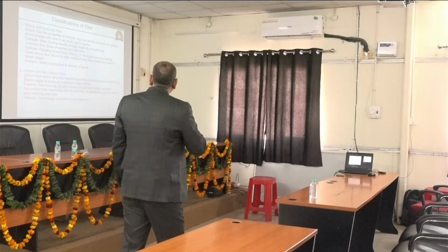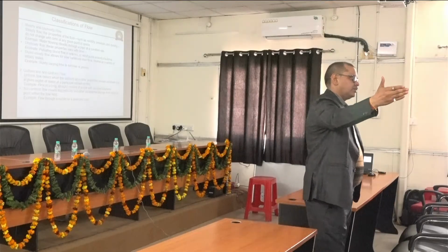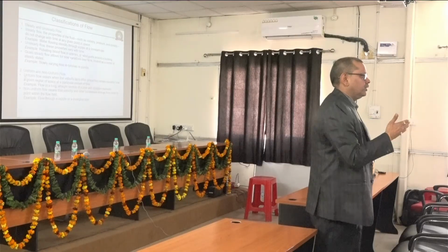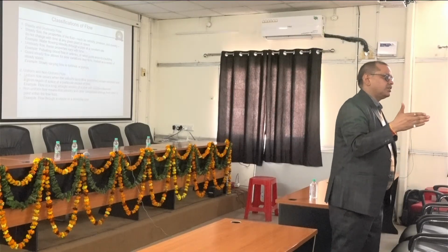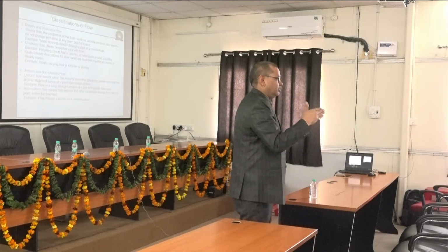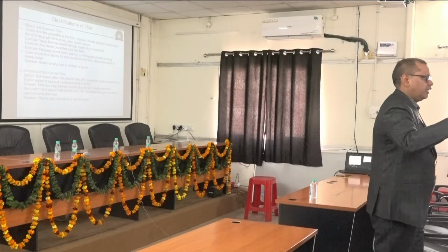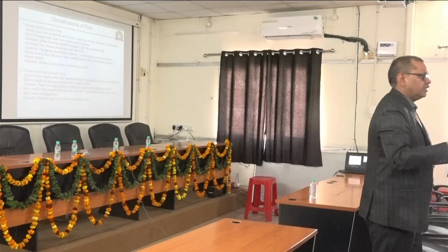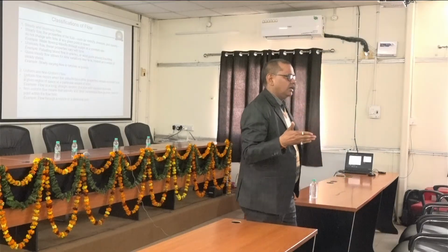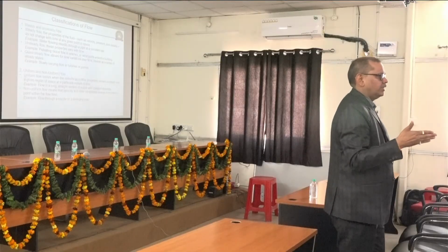Then again uniform and non-uniform, depending upon the velocity. If velocity remains constant throughout the flow design, throughout the pipe, channel or vessel, then it is uniform. If there is change in the velocity, then it is non-uniform. Or if the geometry is non-uniform, using the Bernoulli law you can see that if the cross-sectional area or the densities change at different points, then as per the continuity equation and the Bernoulli law, the velocity will also vary. So when velocity varies, that is the case of non-uniform.